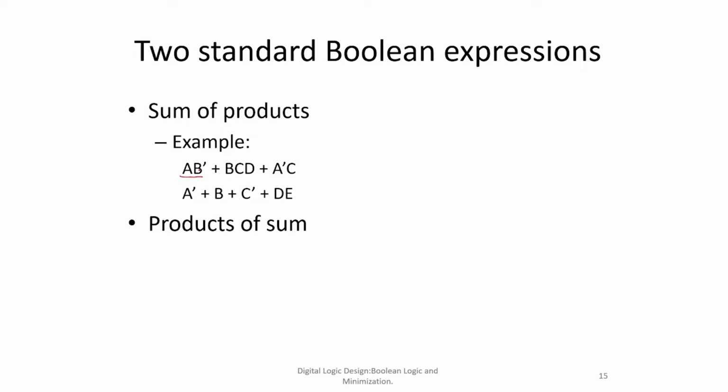But when you combine them, say with an AND operator working over here, this would be called a term. When all the terms are products, and we are taking the sum, that is, doing an OR operation over all these terms, it is called sum of product.